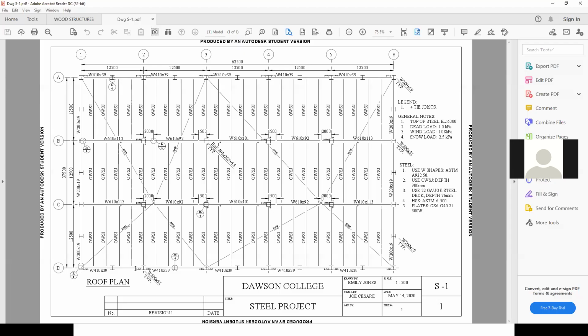Really, the mechanical engineer would say the roof drain. See, he's the one that's going to size the roof drain. You're not going to do it. Neither is the architect. It's a plumbing issue. So therefore, it's the mechanical engineer that decides. He knows, for example, based on the amount of precipitation that we have in Montreal, in a 15-minute period, what will be the flow.